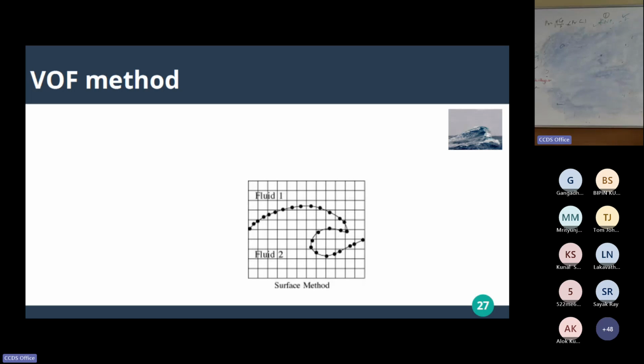The computer doesn't know. Now, how are you going to really say what is that new fluid emerging out of the computation? In some part of the domain, 800 kg per meter cube is not oil, it is still an air-water mixture. You don't know how to resolve them. That is the place where this volume of fluid method really comes to the rescue.